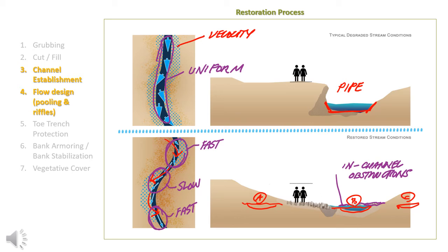By doing that, you're building in some fail-safes against long-term failure of the design, right? You're allowing the channel to move through the soils that it's naturally going to cut through. You're allowing it to find its own pathway. We're also going to shape that, and we'll talk about some of the armoring we can do to shape that flow process in the next slide.